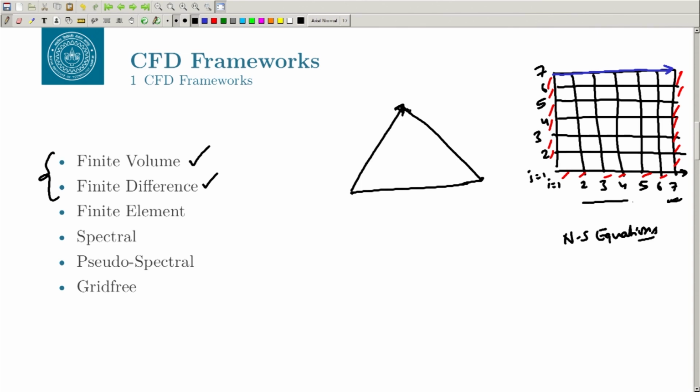So, what you can do rather is basically you can create a grid which is maybe something like this, you can fill in elements the way you want, okay. You might want to ensure that there is a boundary layer close to the wall, okay, that we are able to capture the velocities, the boundary layer properties well, okay. Let us say you made a grid like this. Now, in this you cannot find, if I say that give me, so this is let us say some i j, okay, and if I ask that give me the j plus 1 and i plus 1, okay, and i minus 1 and j minus 1 and so on and so forth, right. So, what is your j plus 1, right. Even if you can give the j plus 1, I may ask you what is give me j plus 2, j plus 3, j plus 4 and so on and so forth.